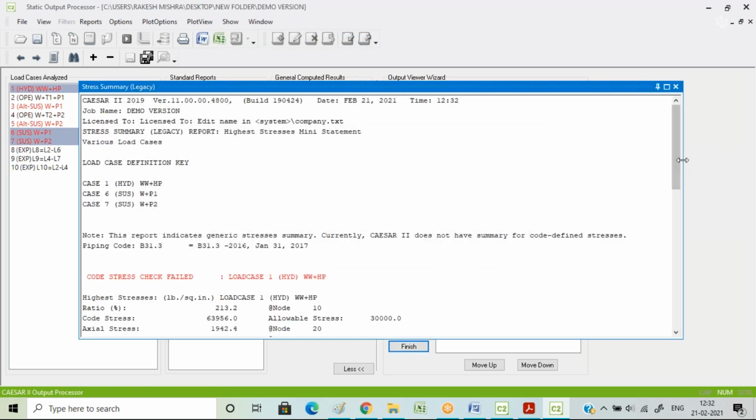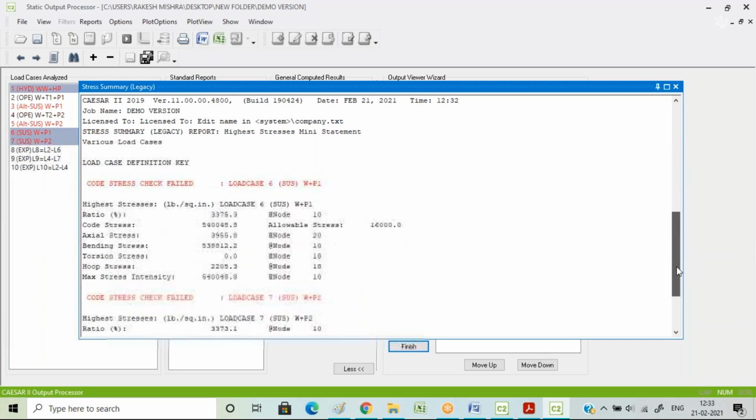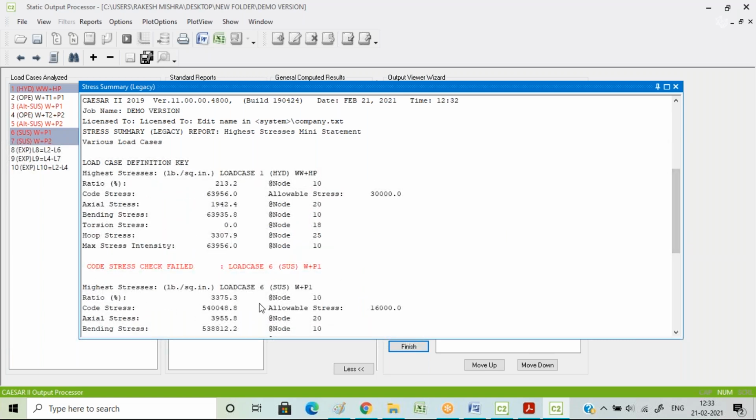Okay, so your ratios have decreased. Obviously, you need to work on your supports now. You haven't supported your line, so it has to be supported properly. Whenever you're getting such vague numbers, say any number which is above lakhs or something, the ratio is fairly high, which is kind of impractical. Obviously, that has to be corrected. Why? Because the entered value might be wrong.